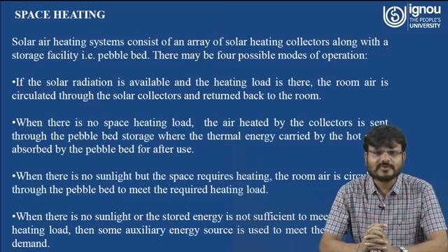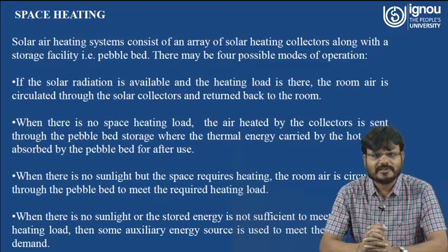First, if the solar radiation is available and the heating load is there, the room air is circulated through the solar collector and returned back to the room. When there is no space heating load, the air heated by the collector is sent through the pebble bed storage, where the thermal energy carried by the hot air is absorbed by the pebble bed for later use. And when there is no sunlight but the space requires heating, the room air is circulated through the pebble bed to meet the required heating load.